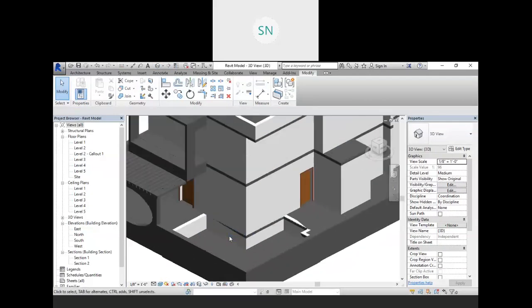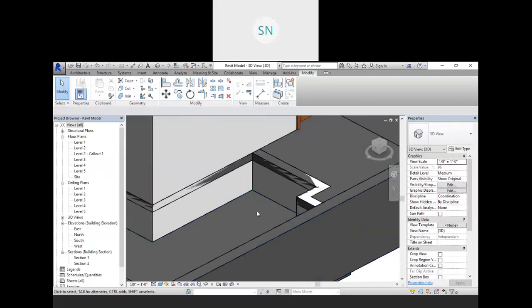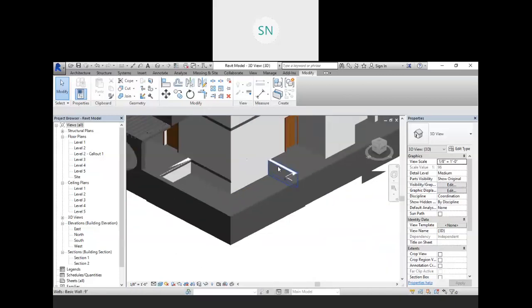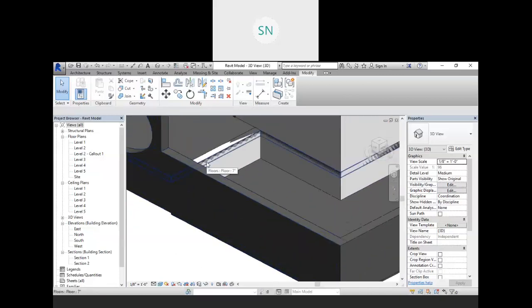Over here you need to create the steps also, okay, footsteps, with the extrusion tool. Create one box and extrude it, then again create one box and extrude it, and create one box and extrude it. We cannot create a stair over here because we just need 2 or 3 steps. So with the extrusion you have to create that. Same over here, right?